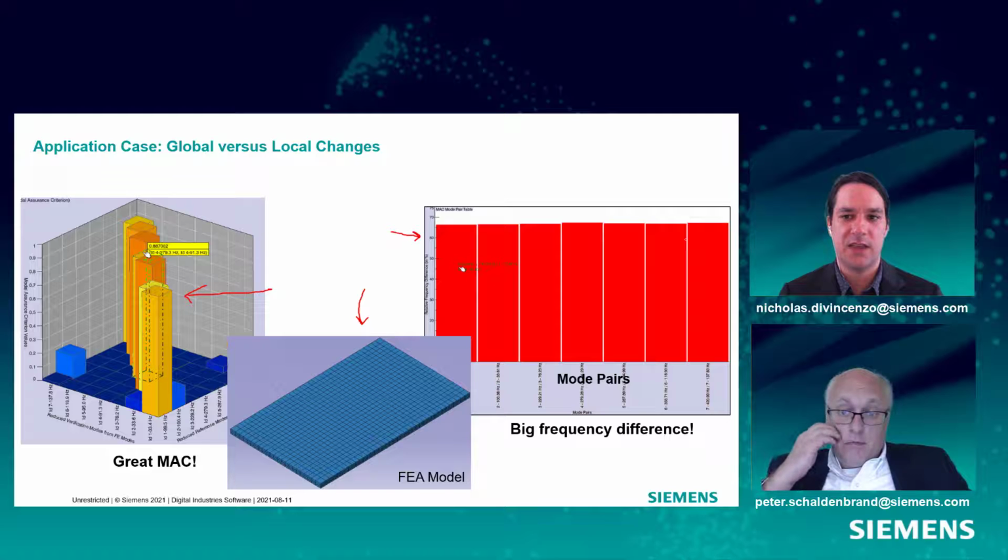So in that first session, we talked about natural frequencies and how for a single degree of freedom system, the natural frequency is equal to the square root of k over m. So I wonder if... K being the stiffness, or Young's modulus. Correct, yeah. And the m being the mass or mass density. So I wonder if in this case, maybe one of those two parameters, either the stiffness of the plate or the mass of the plate, is incorrect.